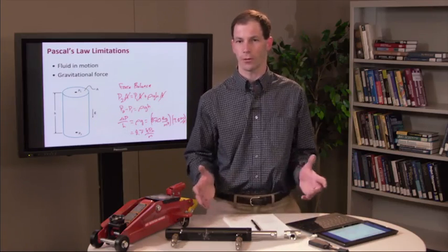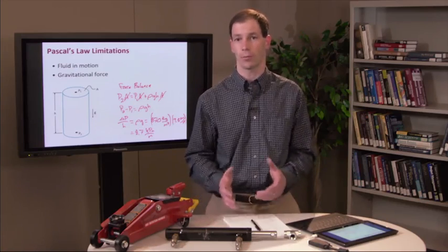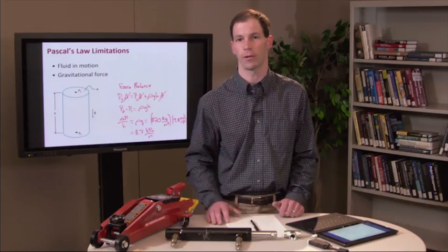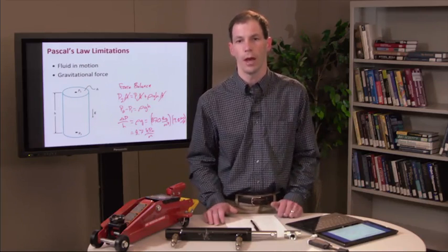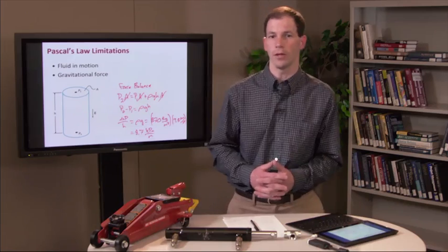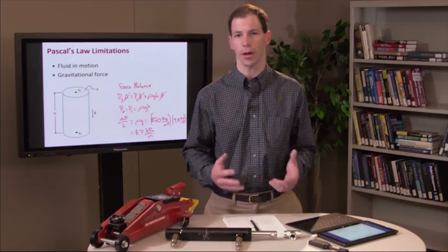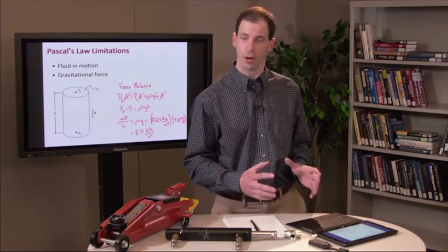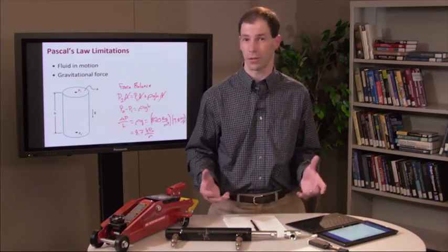And quite often in fluid power systems, it's unimportant, unless you're dealing with perhaps a wind turbine where you have a 100-meter rotor height and you're having a large pressure differential as the fluid's moving up and down in a hydrostatic drive of a wind turbine. One place that it does play a role is in pumps, where we need to minimize the pressure drop coming into the pump. So we'll talk about this pressure drop more once we get to pumps, but for now recognize these pressures are relatively small compared to the hydraulic pressures that we're often dealing with, which is in the megapascals.